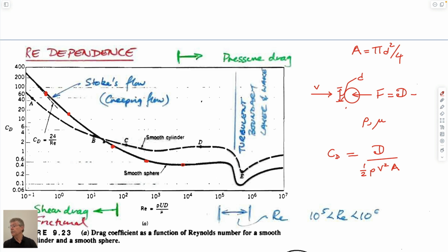And so that's it. So if you don't have a solution to be able to solve it from the integral equations we talked about, which is usually the case, then you can get it from just doing experiments. And the minimum number of experiments you do would be this. So the utility of this is that now you know the coefficient of drag at all Reynolds numbers.